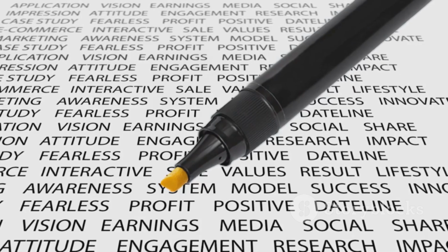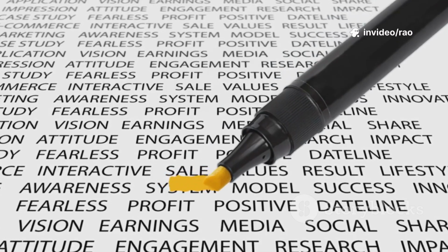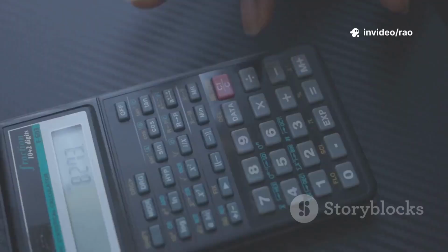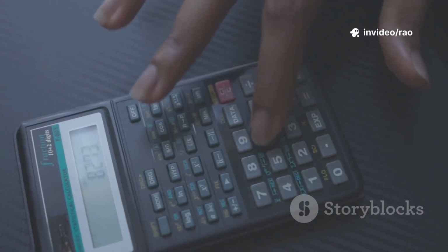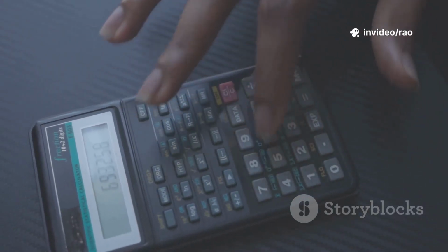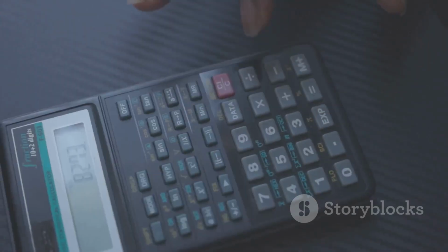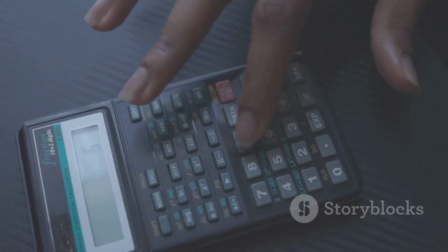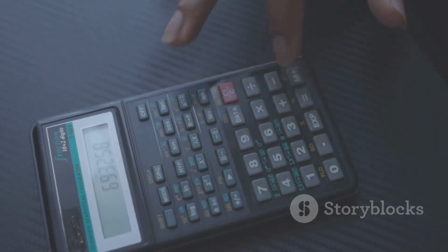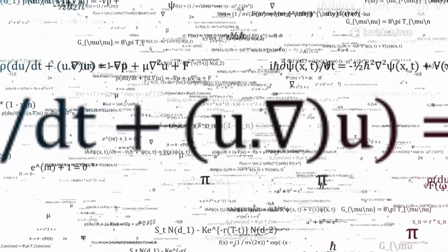Weight of main bars equals total length of main bars times unit weight. Weight of main bars equals 89.04 meters times 0.8889 kilograms per meter equals 79.17 kilograms. Weight of distribution bars equals total length of distribution bars times unit weight.